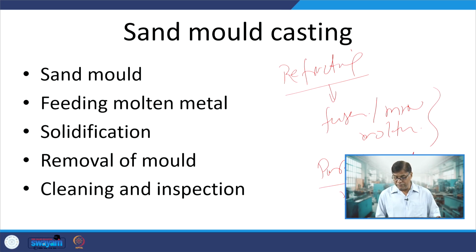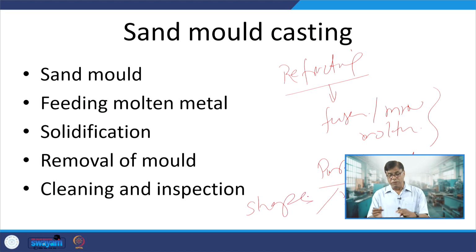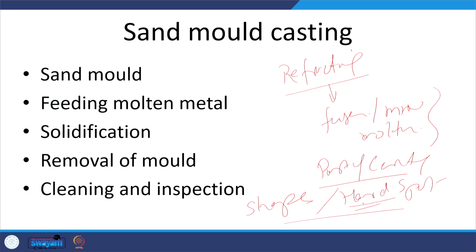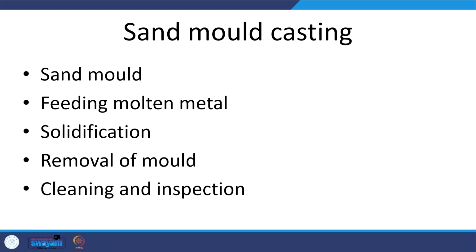So wherever this sand has melted, it will result in the formation of very hard spots, coupled with a change in shape of the casting. So we will be getting a casting of a shape which is not desired, or a casting having surfaces which are extremely hard, difficult to post process or machine. Therefore it is very important that there is no fusion of the mold surfaces during the casting.